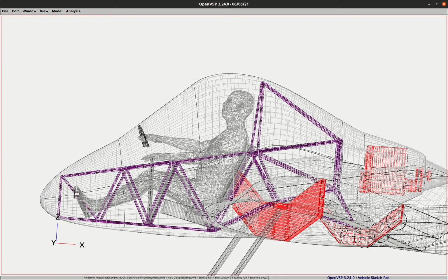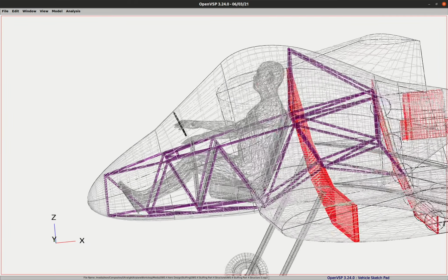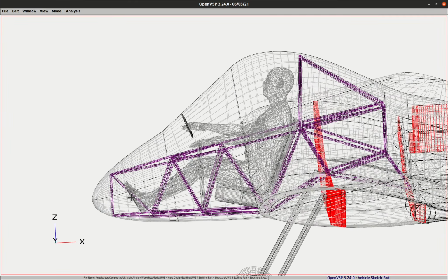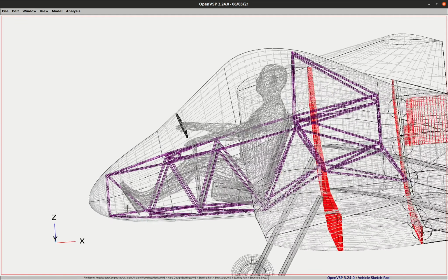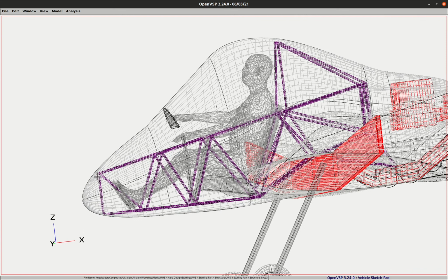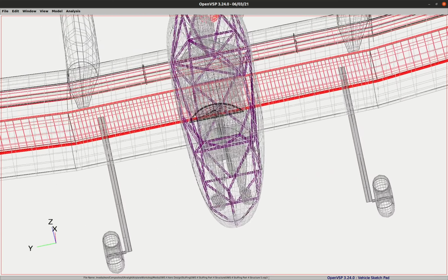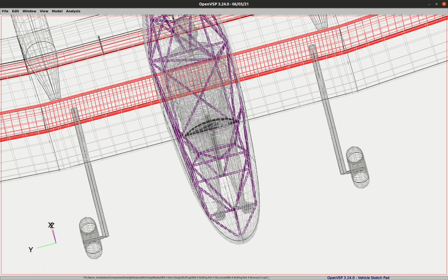We're going to have a spot for our pedals to attach to the frame. And that could actually have quite a bit of force in it. I'm intending to have some toe brakes on here. So somewhere in here there has to be an attachment for that. Now I haven't exactly decided how to do that. I believe this bar here will probably take most of that load. There'll be a little pivot point in here. This bar is actually in the middle. So you can see that bar right here.